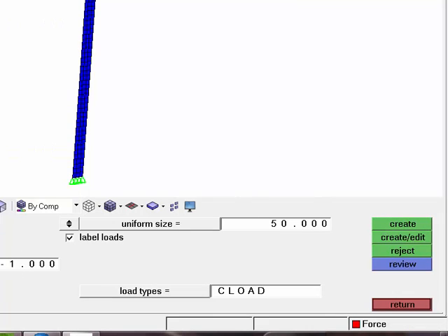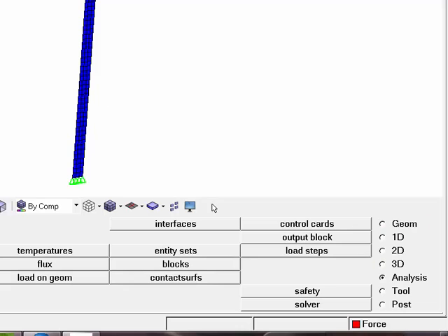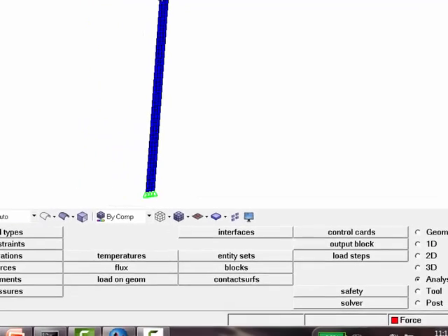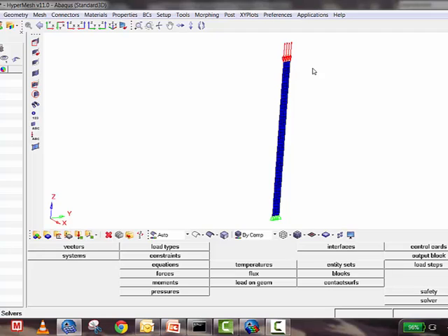So in total I applied minus 4 Newton load on the structure. Now really our load is only in the Z direction, so this particular load is not going to cause any X or Y displacement. So this is also almost like a pin condition. Even though we are not putting any boundary condition, this is exactly a pin condition, because we are giving a specified load in one particular direction which is not causing any other X or Y displacement.